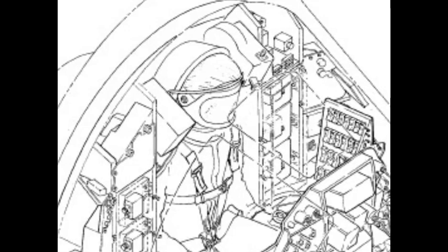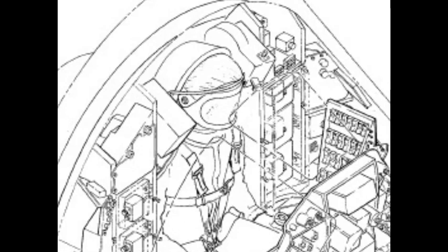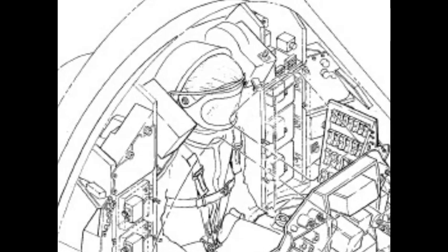The exterior of the clamp ring is covered with a heat shield to protect the clamp ring and explosive bolts from excessive heating during capsule launch. A layer of thermoflex insulation is bonded to the interior of the heat shield. The heat shield is attached to the clamp ring with screws. 6 cable straps bolted to the pylon structure and clamp ring heat shield aid in capsule pylon separation by retaining the clamp ring segments to the pylon when the explosive bolts are fired.